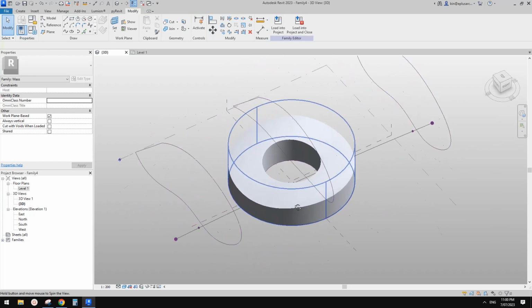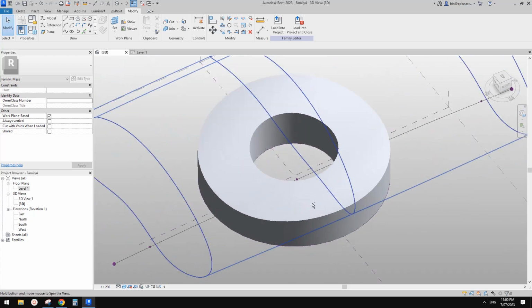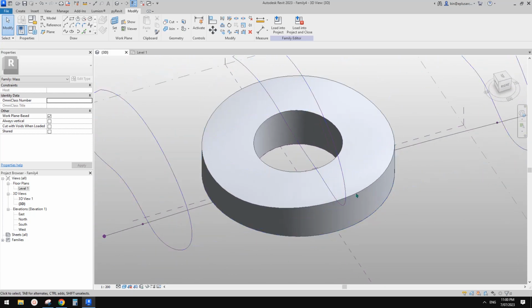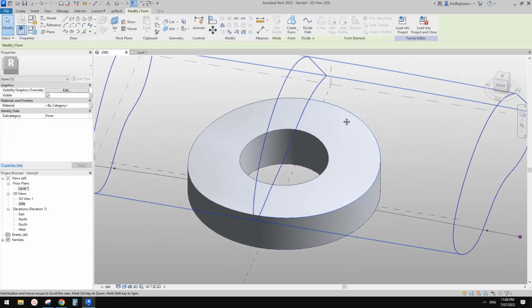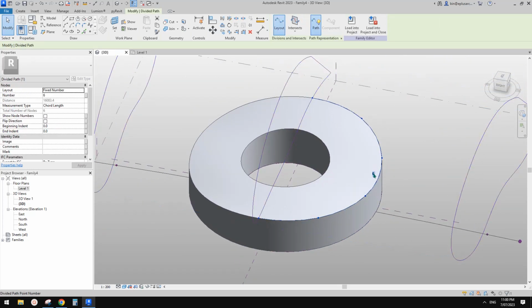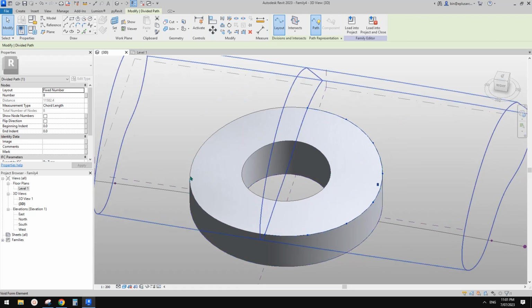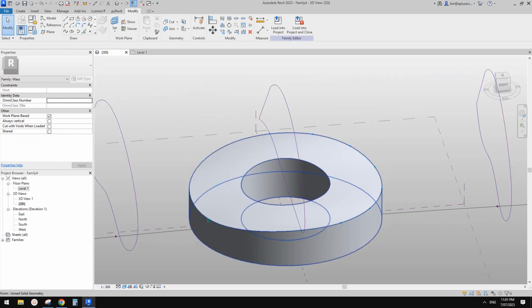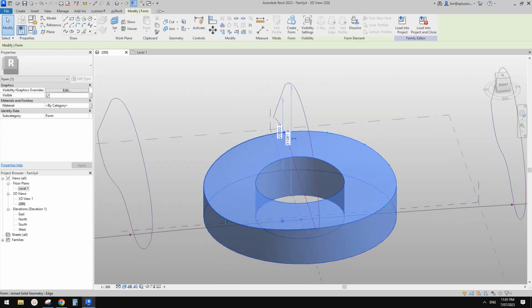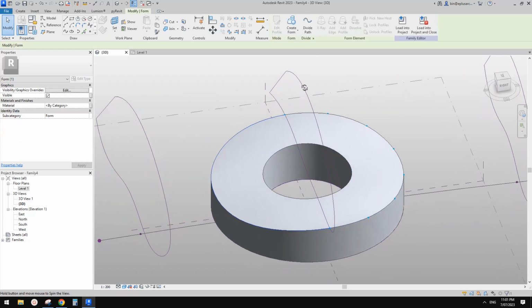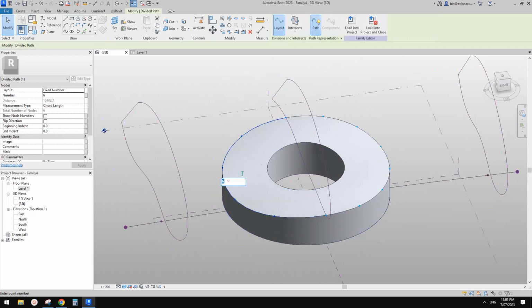So now we have this shape, and the next step is we're going to tab select the edge, so you can see the edge, and then we can use divide surface. I'm going to just use a smaller number because my computer is slow, so better not kill it. I'll just use 8.